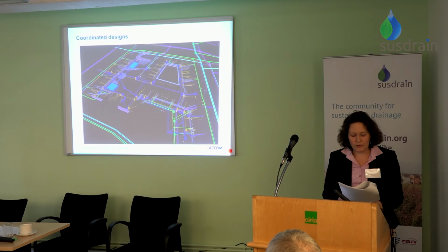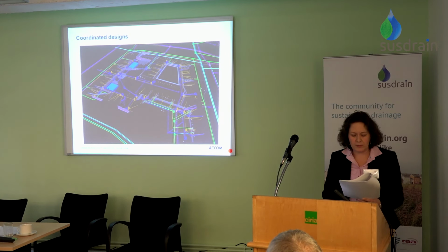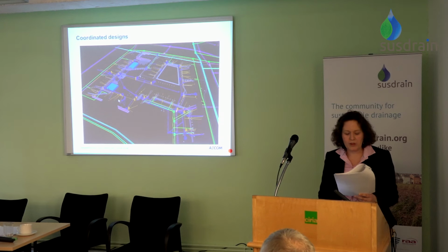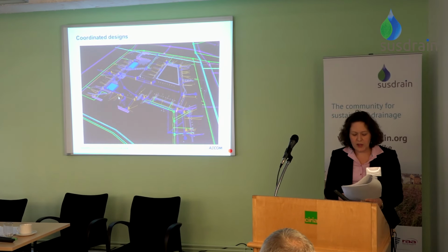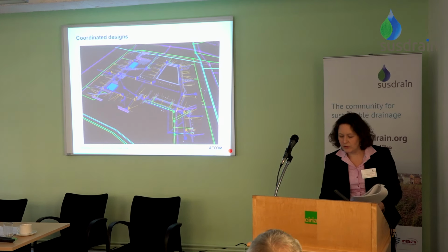This is an image from Lot 5, where the university ran a design trial using BIM. On this plot, we modelled in 3D every rainwater downpipe connection, which is shown in blue, passing under the buildings here, and every soil vent pipe connecting to the foul network, modelled in brown. We also modelled the incoming services to the plot, which included the potable and non-potable water network connections.